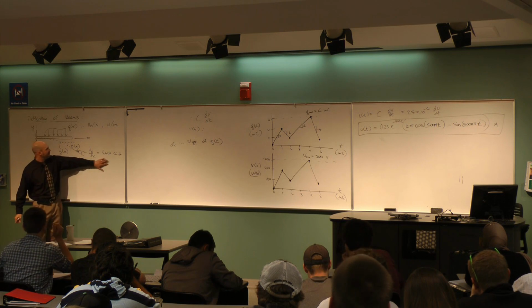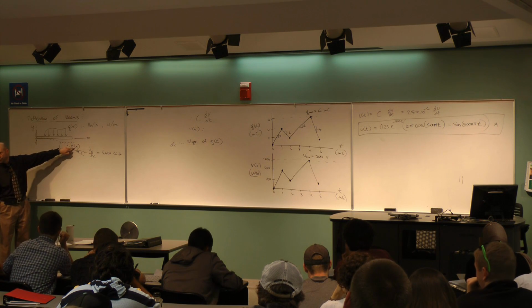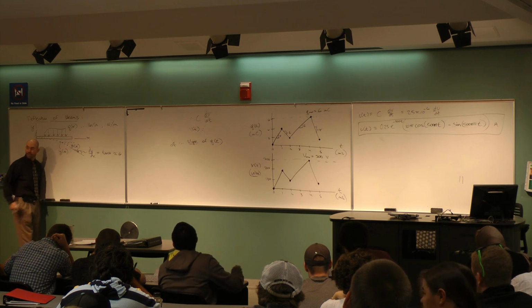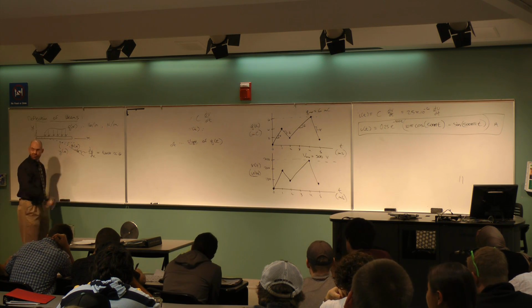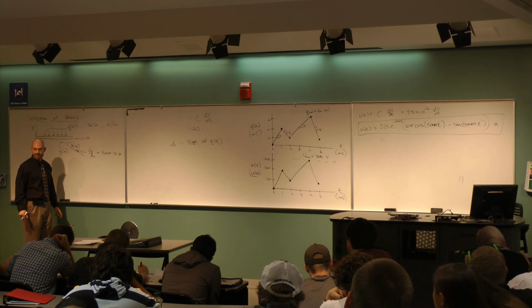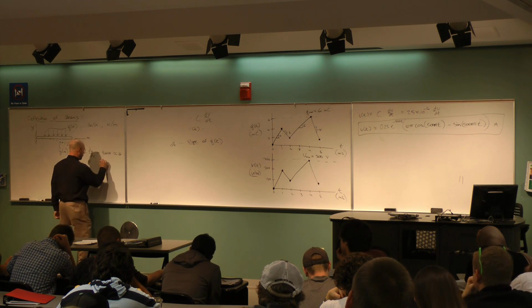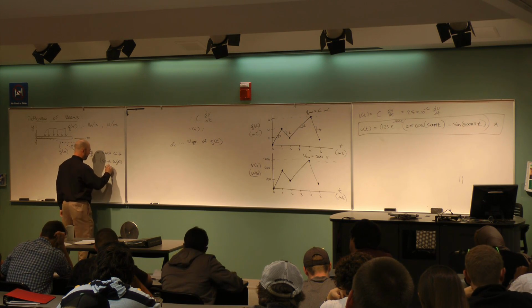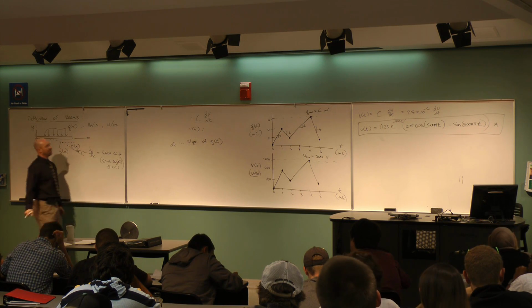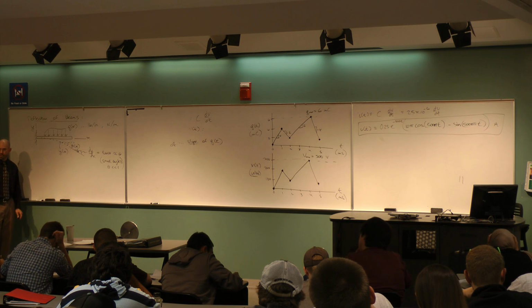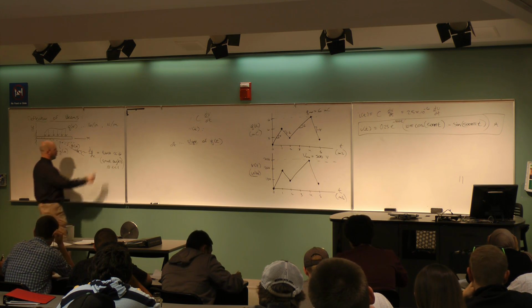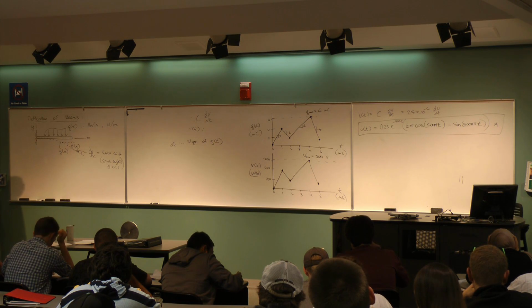So the reason I make this point is that theta of x, the slope of the beam at any given point as an angle in radians, is actually just the derivative, dy dx. This is true for small angles, in other words theta much less than 1, where 1 is the dimensionless measure of an angle in radians.